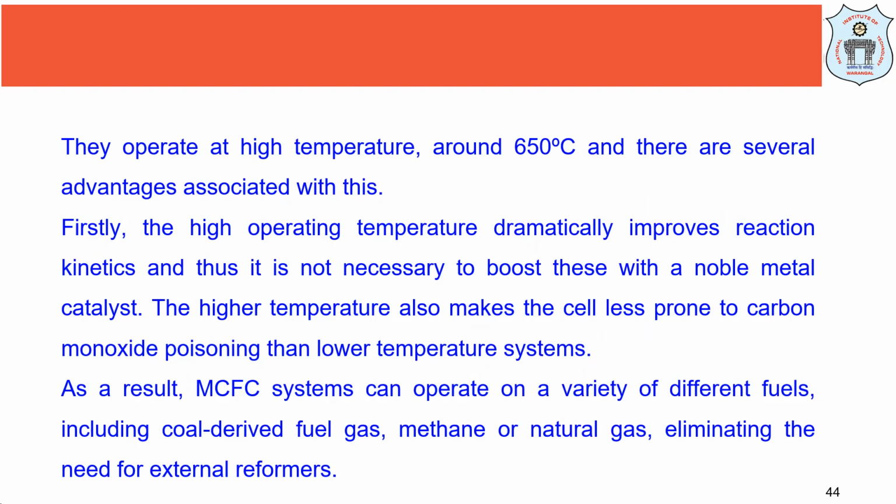Firstly, the high operating temperature dramatically improves the reaction kinetics. Improved reaction kinetics is the major advantage, and it doesn't require boosting with any costly noble precious metal catalyst. This high temperature also makes the fuel cells less prone to carbon monoxide poisoning than the lower temperature systems.